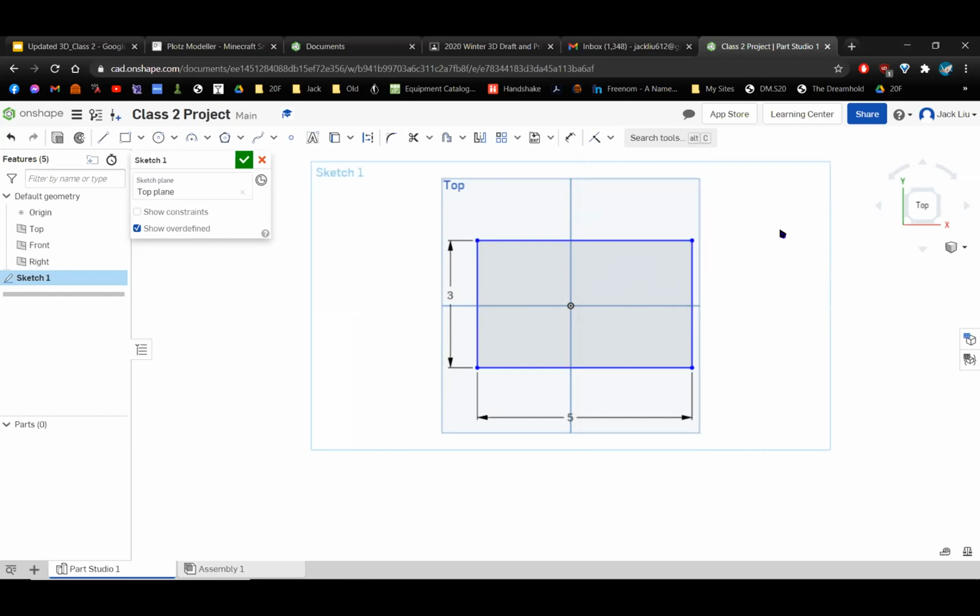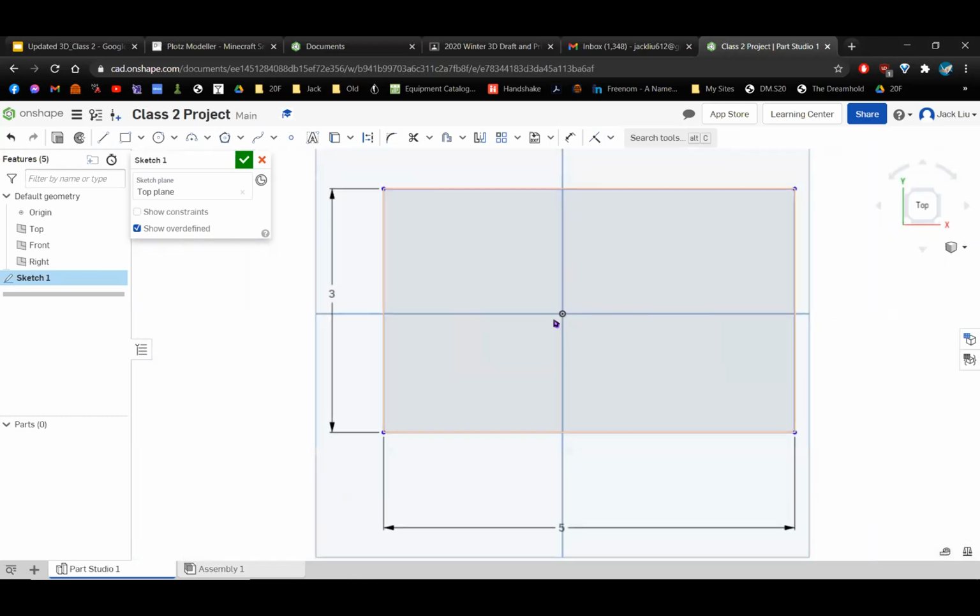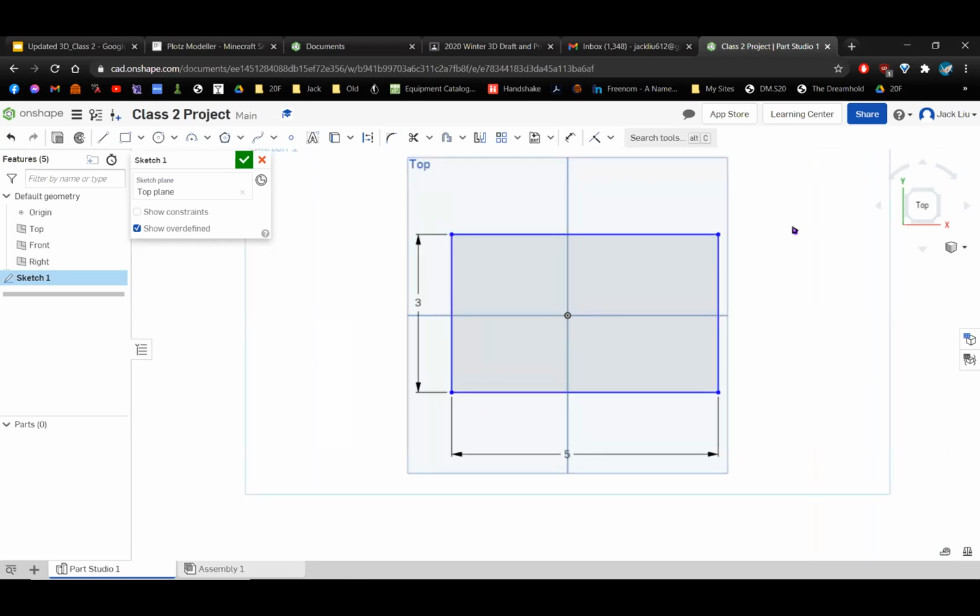One way I can do that very easily is with this coincident constraint, which makes two things at the same location, right? When we're just starting out with a blank document, the only set point in our whole document is the origin point, the special dot right in the middle. This is our only well-defined position in our whole document. So I'm just going to use that to define our rectangle. I'm going to say my bottom left corner of my rectangle has to be coincident with the origin.